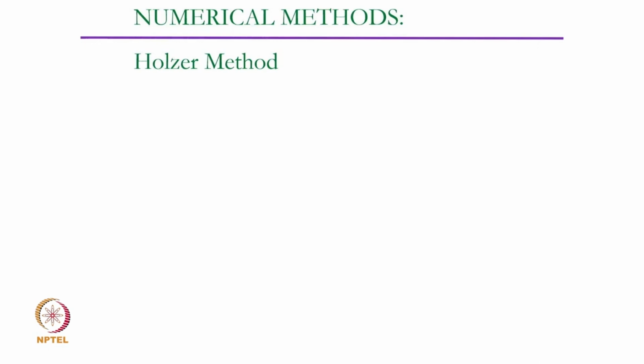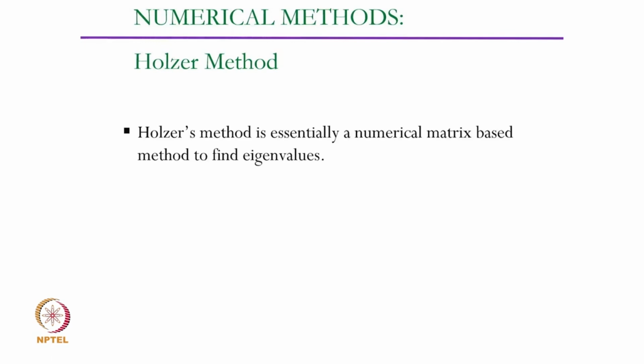So we'll start with the Holzer method, essentially designed for solving torsional vibration problems, but going by the way it is formulated, you can also use it for longitudinal or axial vibration problems.